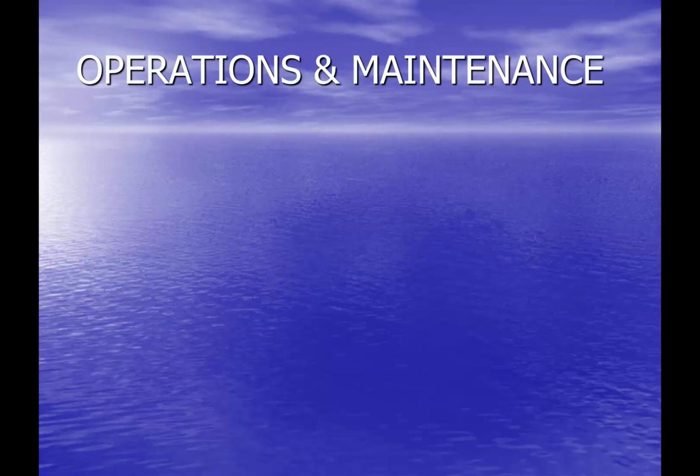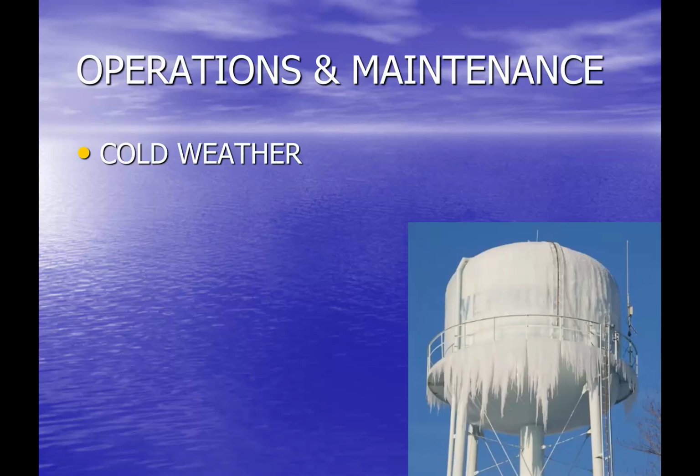Some other operations and maintenance concerns or practices that we need to be aware of. When you get into cold weather climates, they can be a pretty significant issue for elevated tanks, both on the exterior as you see in this picture, but really the water on the interior. And it's really bad for the reservoir if you allow freezing conditions of the water within the tank. Ice that might build up can damage the structure of the interior of the tank.